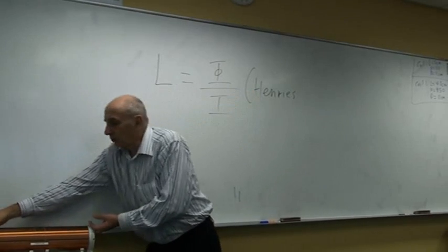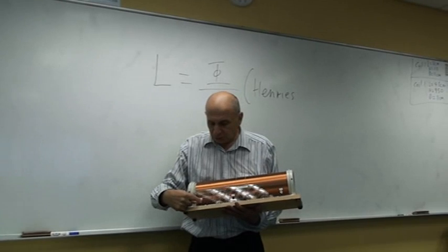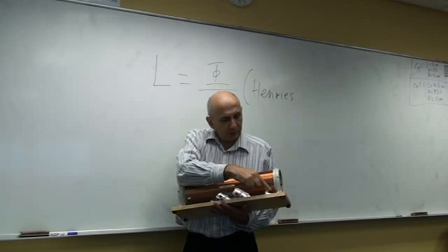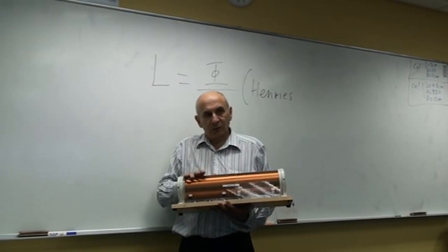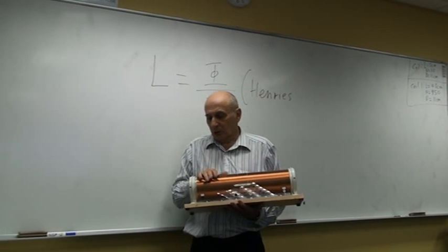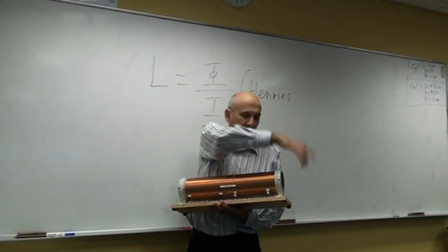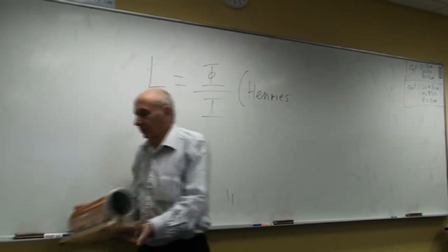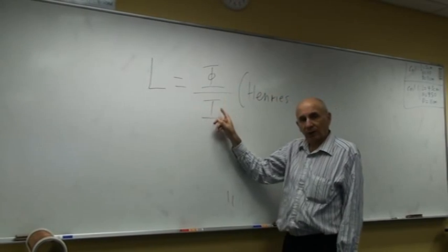Now in lab number 4 we're going to be dealing with this coil here. So current's going to go into this terminal, go around these coils and come out of here. So we've got current flowing in this coil. Now, as I've told you in the lecture, whenever current flows, you always get a magnetic field. There's going to be some magnetic field comes out of here, goes around, and then back in here again. Magnetic field flows around here. Now, inductance then tells you how much magnetic field you get for a given current.